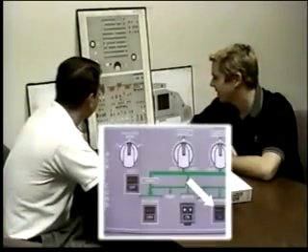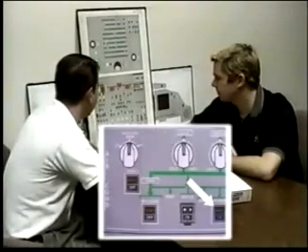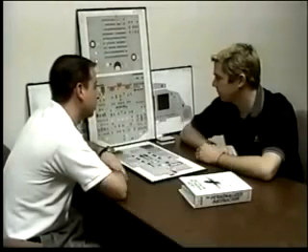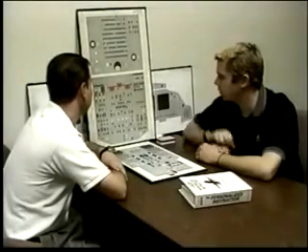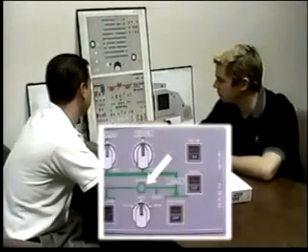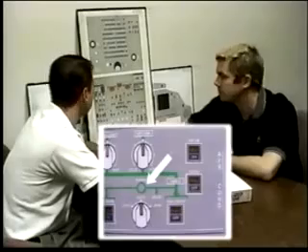APU bleed. APU is available. You select APU bleed to on. Describe to me some valves that will open, valves that will close. Okay, when the APU bleed valve is open, the engine bleed valves will close, and the cross bleed valve, if it's in auto, will open.